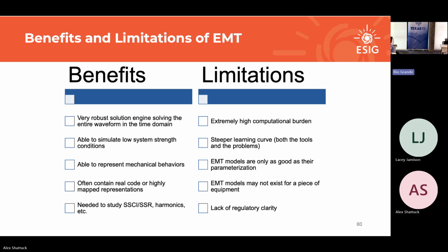Is it 2020? Whatever. Well, they used something that was reasonable. So let's say 2020, right? If you retroactively apply to 2020, if you interconnected afterwards, your manufacturer, we know your manufacturer built the EMT model, just go get it. That's one way. If you say every single inverter-based resource who's ever connected to my system has to produce me an EMT model in a year, that is a requirement that goes the opposite of what you're trying to do for reliability.